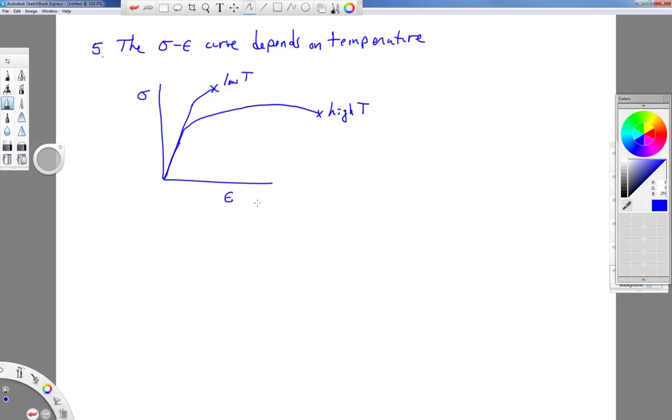Another good example of this, it's been speculated that the steel that was used in the Titanic had a ductile to brittle transition temperature that was fine in the warm water port where the ship was built, but dipped below that transition temperature in the icy water when it was near the icebergs. And so when it hit the iceberg, instead of it deforming as much, it simply cracked quickly, and those cracks ran very easily in that material. So that would be an example of steel behaving more brittle at a certain temperature as opposed to a higher temperature.